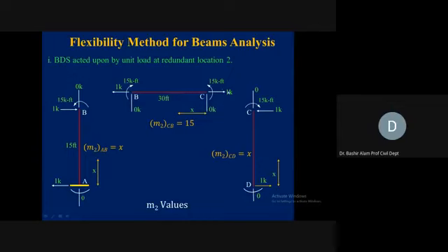BC now we need to analyze. 1 kip rightward, so 1 kip leftward. Horizontally the member is in equilibrium, 0, 0 in equilibrium. 15 kip-ft can be resisted here, 15 kip-ft. Moment is also in equilibrium. Joint B, to put this in equilibrium: 0, 0, 15 clockwise, 15 counterclockwise, 1 leftward, 1 rightward. Similarly, we now transfer this to joint A. 0, 0 horizontal, it was rightward, this is leftward, this is counterclockwise.